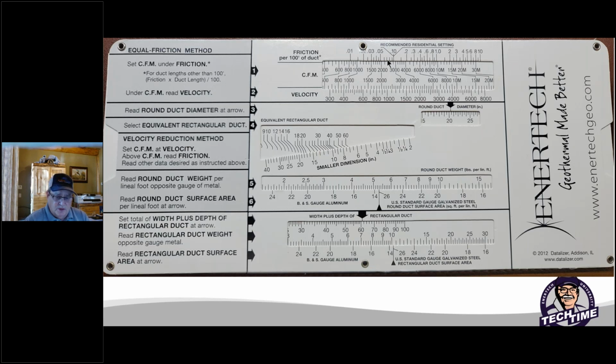So one of the things I used to do was a 5-ton system, let's say, had 2,000 CFM airflow. So I put in 20, make sure I had 20 registers if it was a non-zoned dampered system. And keep your customers happy, eliminate some of the noise.